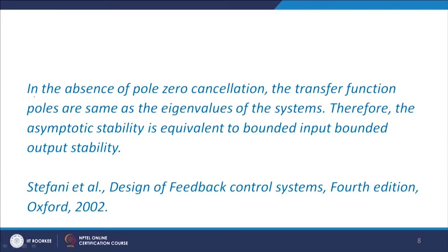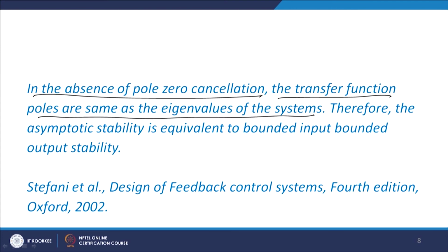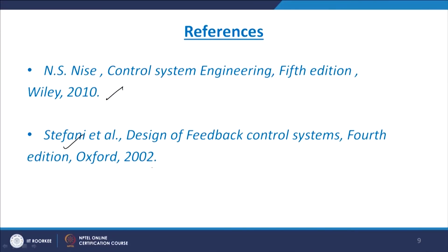So here it is written, in the absence of pole zero cancellation, the transfer function poles are the same as the eigenvalues of the system. Therefore, asymptotic stability is equivalent to bounded input, bounded output stability. Now these are some references.